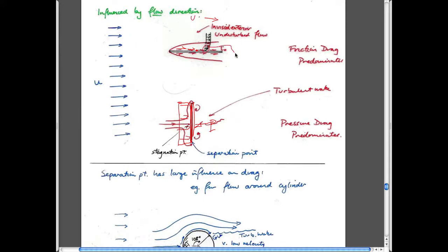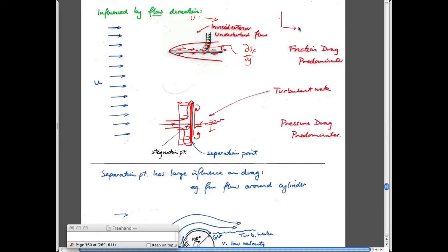But obviously this value here is going to be a change in velocity in the x direction, and it changes with y, right? So there's a high gradient here. This gradient, if you draw it, if you imagine this as being ux, it's zero at this point here, and it curves off here. This is the y direction. So at this point here, there's a gradient dux/dy, which is quite large, potentially. And we know from Newton's law of viscosity that if you multiply that by this, it gives you something you've already seen, right?